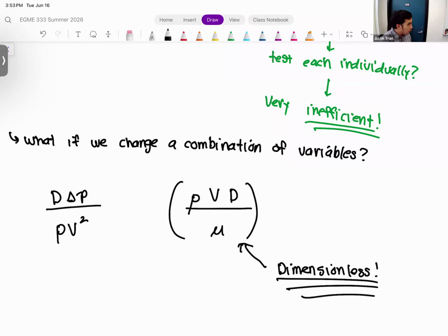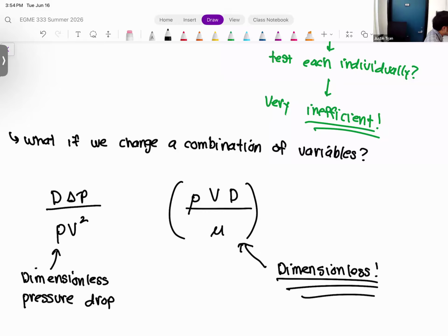and then you take your pressure drop and you also make it dimensionless, where we're taking the exact same variables that we use, right? So you can see here, we took the pressure drop, we multiplied it by the diameter, we divide by the density times the velocity squared, right? So that's also going to make it dimensionless, okay? Right, we have this new function phi, right? So this phi here means function of.